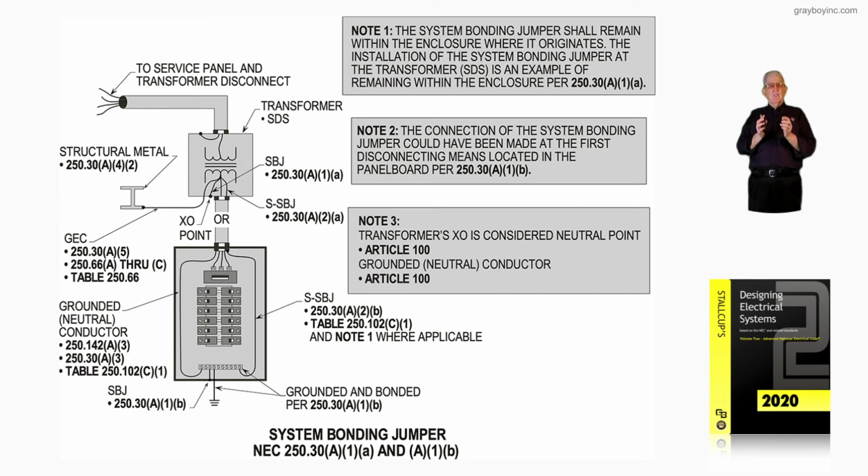Now, I believe that this covers the grounding procedures using a system bonding jumper, with metal conduit all the way from the transformer to the equipment. If it's metal conduit, you have to bond at the transformer, or you have to pull an isolated neutral and a grounded conductor connected to ground there. I'm talking about to the metal enclosure because you're grounding at the service. So remember one other thing, if it's a non-metallic conduit between the transformer and the equipment, you can bond at the equipment as well as at the transformer. You wouldn't have to, but you could. So just keep that in mind.